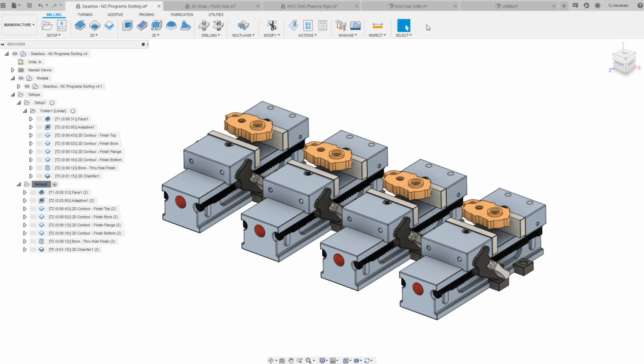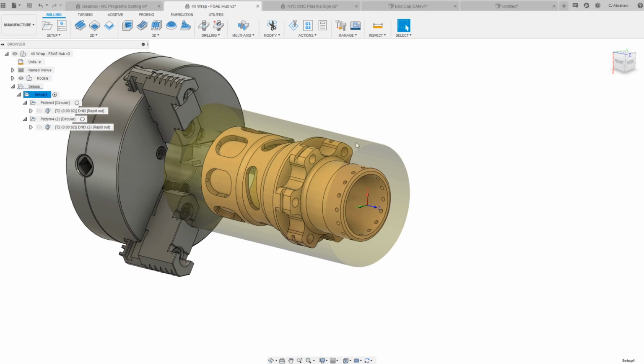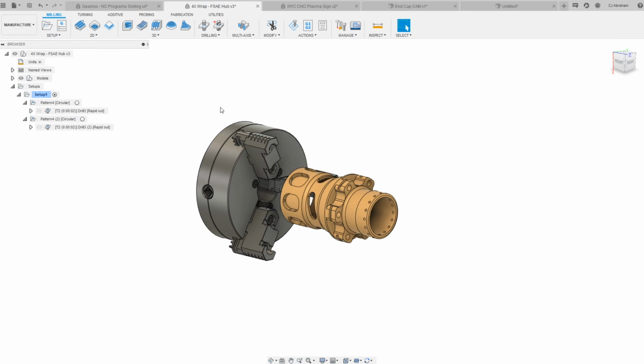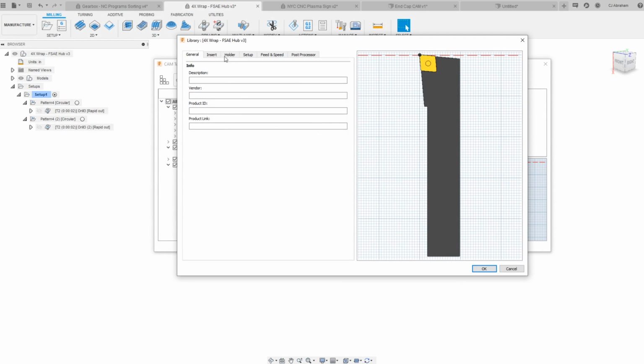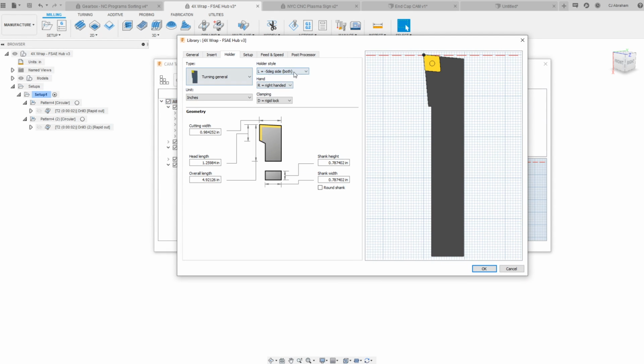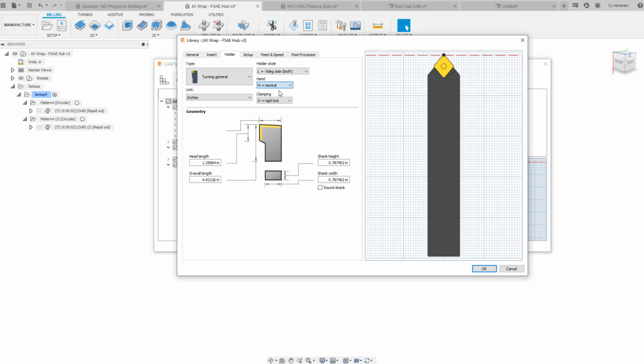Okay, yeah, so let's cover turning the tool at 45 degrees for B-axis machines. So I don't know what the particular tool that was used in this case, so I'm just going to create a generic one. And I'm going to create a neutral tool to do this.